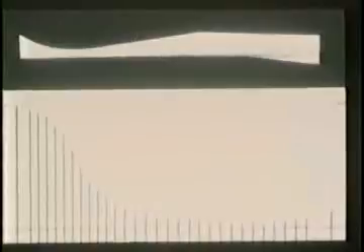For steady acceleration from subsonic to supersonic velocity, the area of our channel or of any stream tube must first decrease and then increase. There must be a throat. Since the fluid is accelerating at this throat, the Mach number there must be equal to 1, and the channel is necessarily choked.